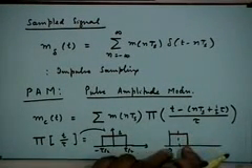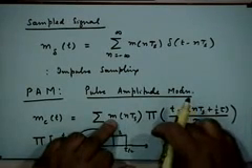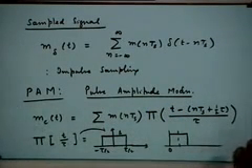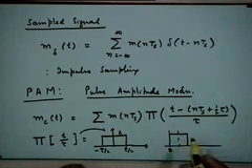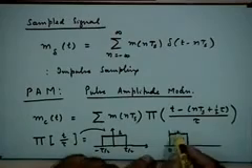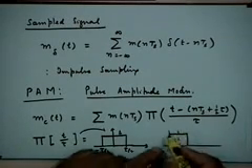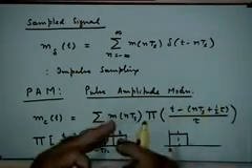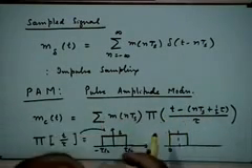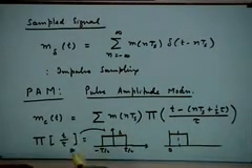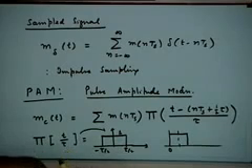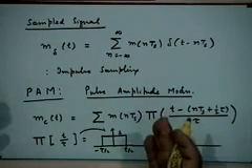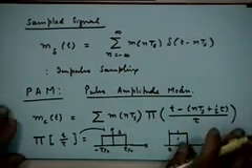This is a pulse that you are transmitting, whose amplitude is governed by the message value at that time instant, right. What happens in natural sampling? This pulse is not flat top. Its amplitude varies in proportion to the variation of the message in that time interval, right. But that is not what we call pulse amplitude modulation. Pulse amplitude modulation is basically flat top sampling, right.